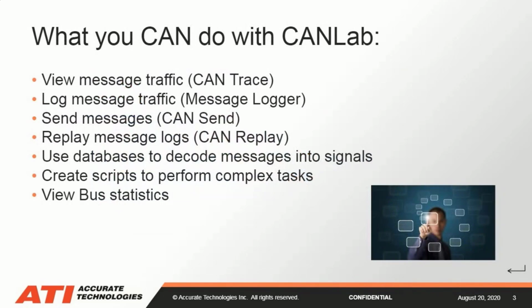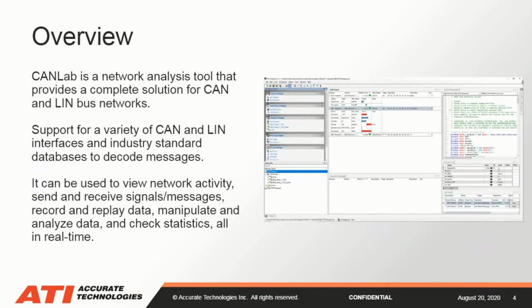So what is CANLab? CANLab is a multifunction bus analysis tool that allows you to send messages, replay messages, collect logs, view CAN traces, view bus statistics, and incorporates a C# scripting environment right inside the software to enhance your functionality in the field. So CANLab is a complete bus analysis tool. It allows you to access CAN, CAN-FD, and LIN networks.